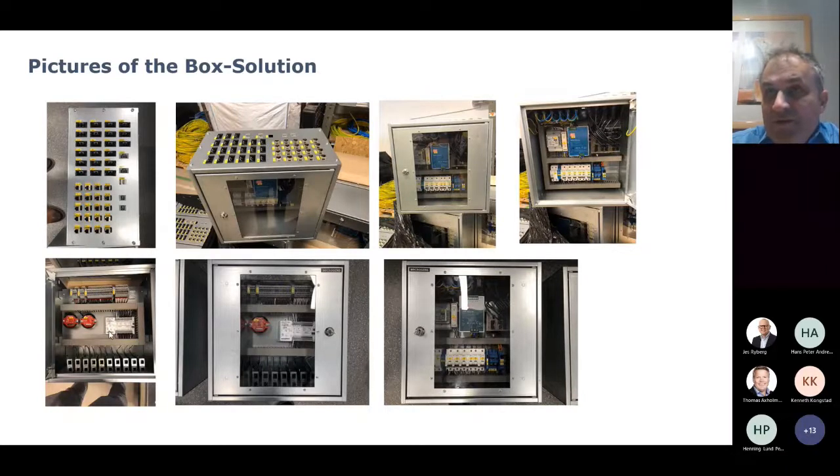The smart I/O controller does a similar thing to the smart light controller. It is fed by PoE, and you can connect conventional signals like analog inputs from 0 to 10 volt, or digital inputs, dry contacts. You can feed analog outputs 0 to 10 volt for valves, or digital outputs to switch something directly.